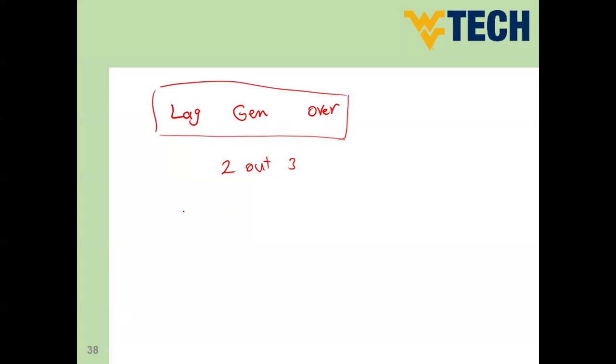Which means, if I say lag motor, I changed just one right now, so I have to change the other. So this is going to be under. So if the motor is lagging, it would be under excitation. If I said lead motor, I changed 2 compared to here. Instead of lag, I made it lead. Instead of generator, I made it motor. So we changed already 2 out of 3. So you have to keep the remaining term. So in case of lead, in motor case, it would be over excitation. So this is the way, guys.